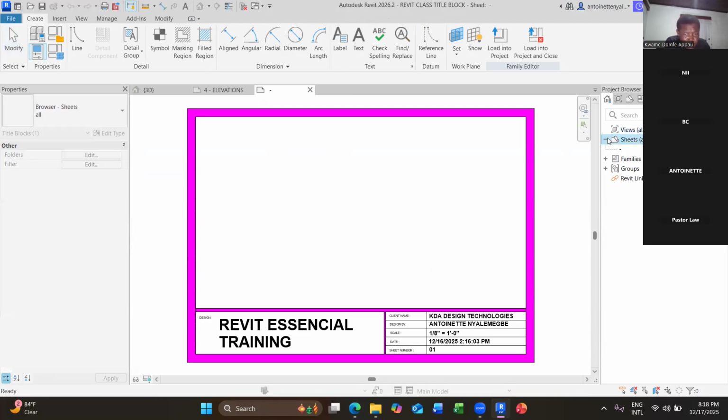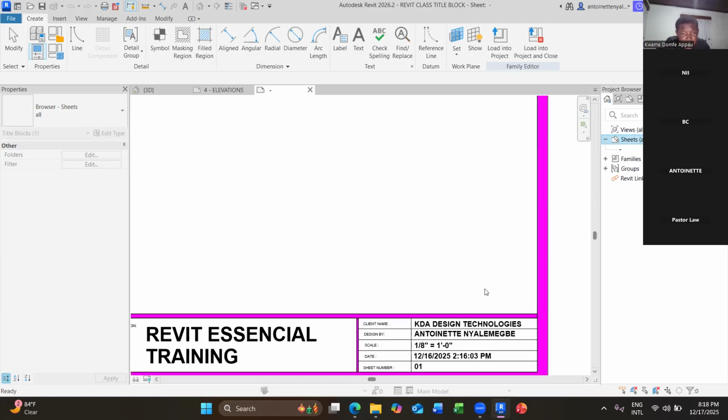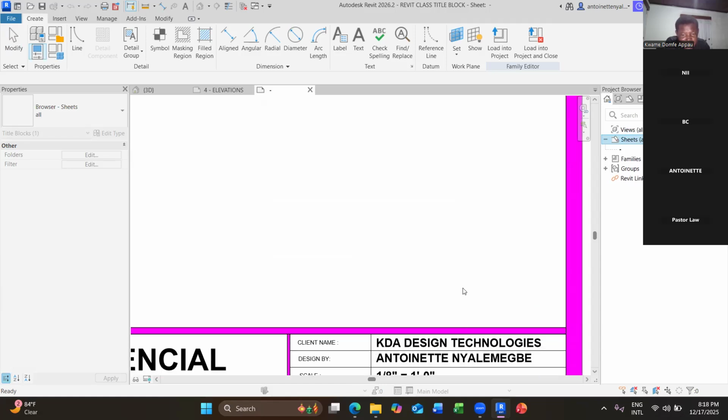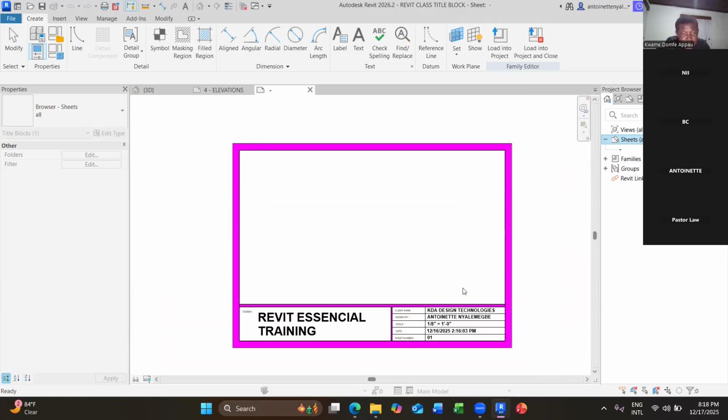First comment. The section that contains the details of the title block is consuming much of your sheet. It's too big, leaving a small area for the drawing to fit. You should come below, just up to where the scale is. So reduce the font sizes.